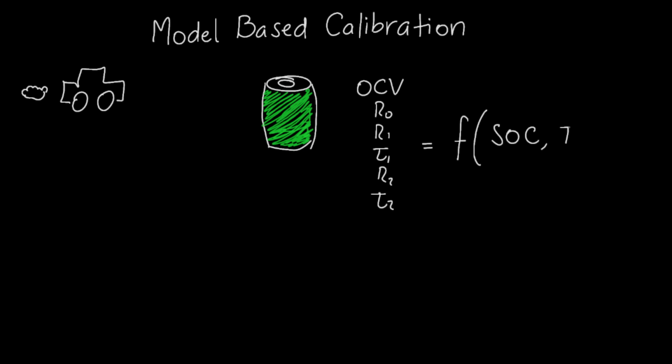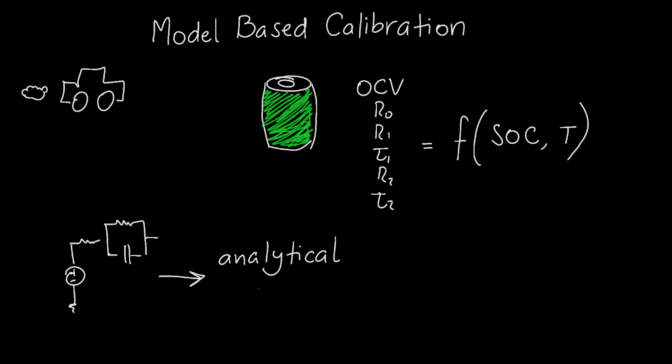What makes this tool especially efficient is the fact that the parameter estimation does not rely on a simulation of the experiment for the construction of the objective function in the optimization. Although the optimization is performed using nonlinear least squares, the method exploits the relative simplicity of the mathematical representation of the response of the equivalent circuit by calculating the objective function gradients analytically.